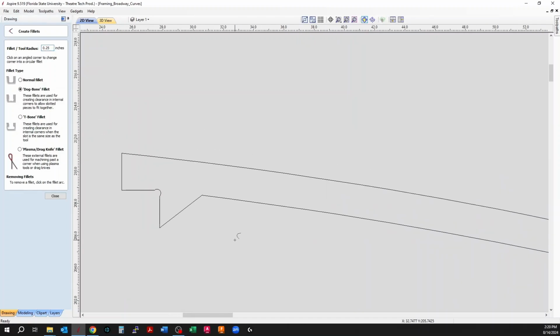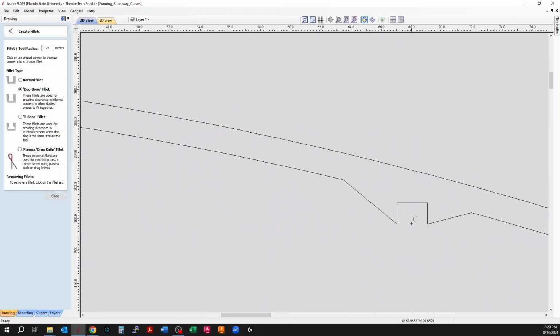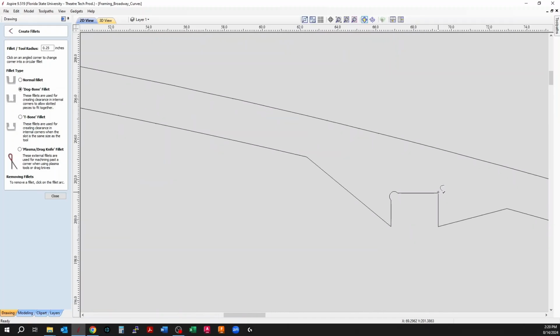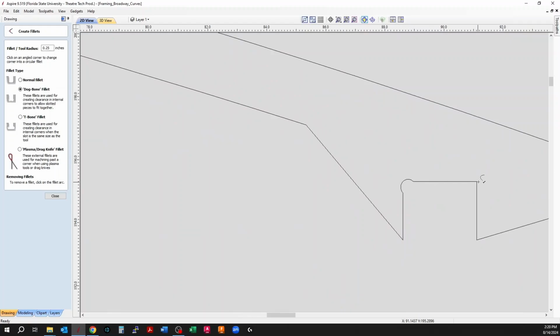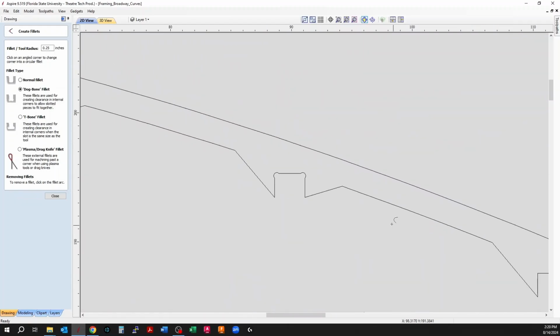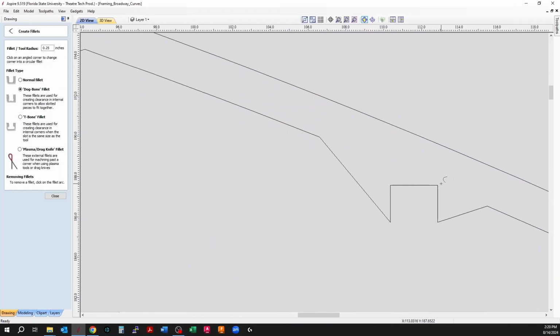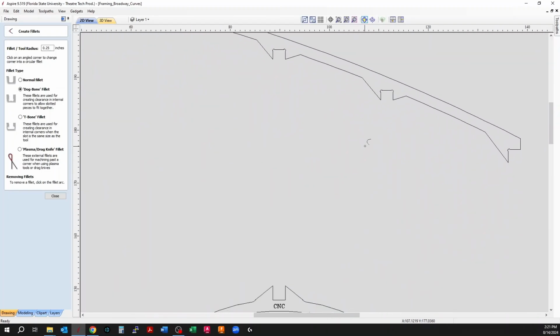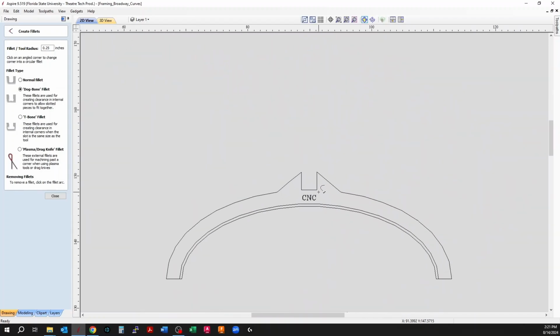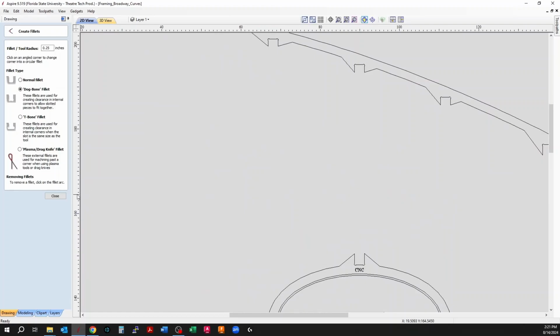And so anywhere where you have one of those sharp corners, you want to round it over, because the bit will do this. It'll follow the profile, and the bit will give that little rounded nubbin. It'll kind of do a little push in on each of those little spots. And so as it does that, it has room for your square shape to go into place.